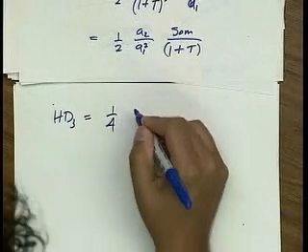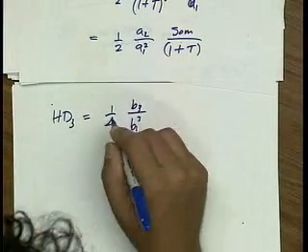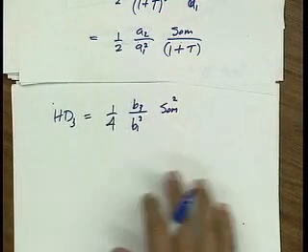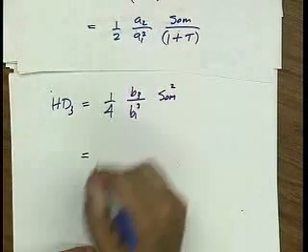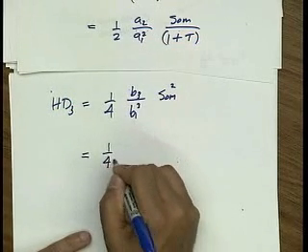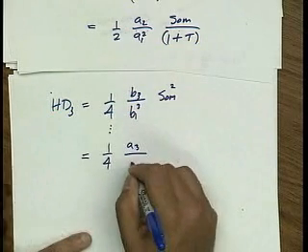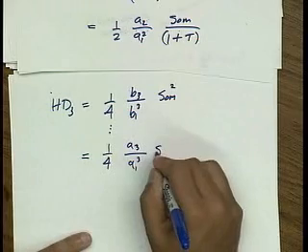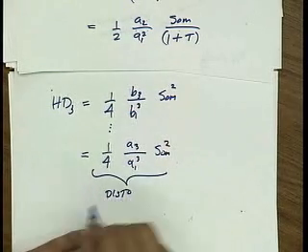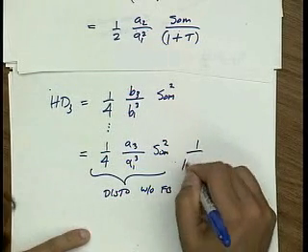HD3 we derived last lecture in terms of the output is B3 over B1 cubed times the output level squared. Okay? And I plug in all the equations that I derived. Again, I won't bore you guys with algebra. And the answer comes out to, I like to write the answer in terms of the distortion of the circuit without feedback, times 1 plus t.